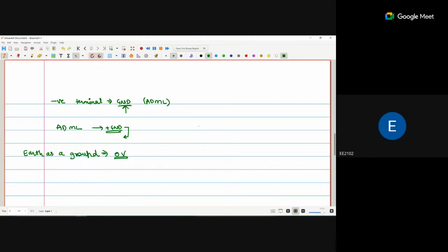If we are talking about Rajasthan, the water in the soil is very less, so you are getting a different voltage. You consider that this voltage is 0. In Chennai the soil is different; there is always moisture because of the water. So the resistance is different, the voltage is different. Every particular place has a different earthing voltage. But what we do is assume that this earthing, whether it has 1 volt or 2 volts, is our ground level or reference level. But the voltage is not 0 everywhere. Understood?